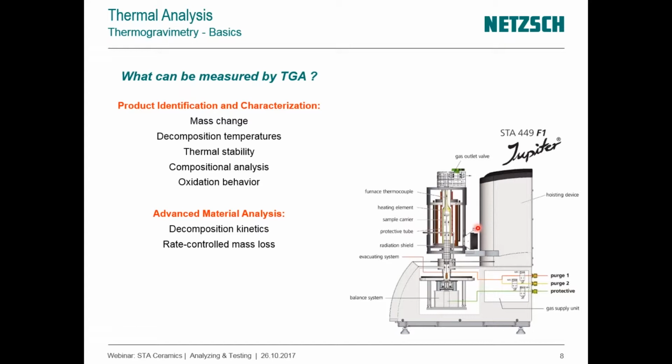Of course, there is no furnace which can handle this in one step, but in principle there are existing combinations. You can even attach two furnaces to the same instrument, so you can switch between the furnaces for measurement. So you can, for instance, apply a machine with a furnace going from -150 to 1000 degrees C, and a second furnace going from room temperature up to 2000 degrees C.